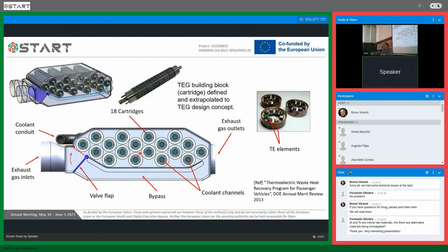We instead sealed the device in argon, as an example, so in an inert gas. Each of these cartridges of thermoelectric material were sealed with an inert gas, and the larger cylindrical device had something similar. That may have been really challenging going into mass production, but that is what was done on these initial demonstration parts. But tetrahedrite would require some form of protection.